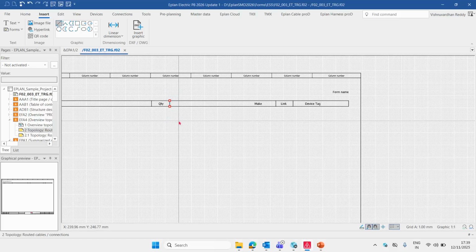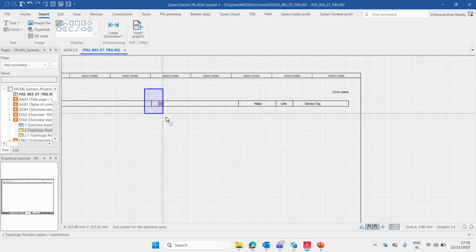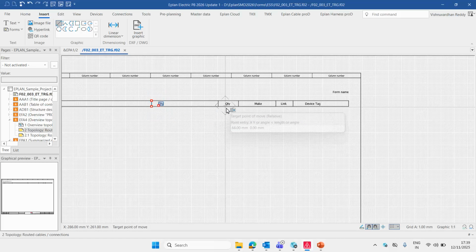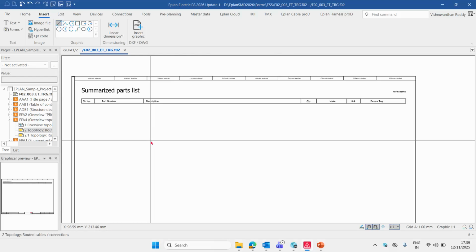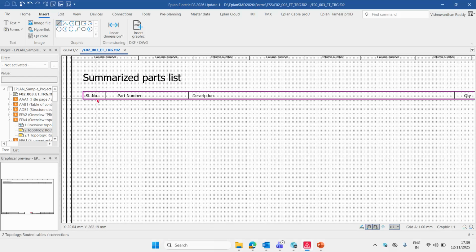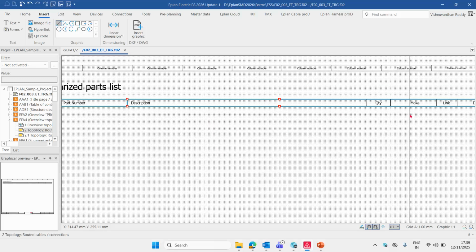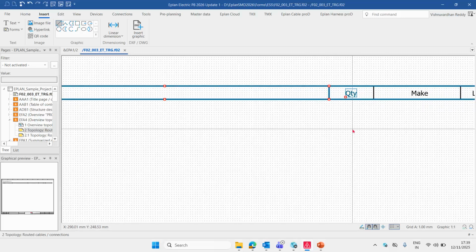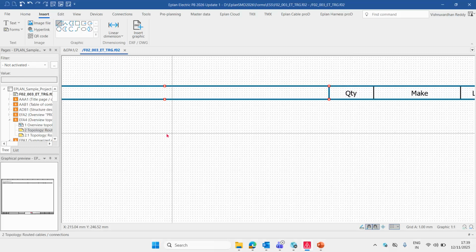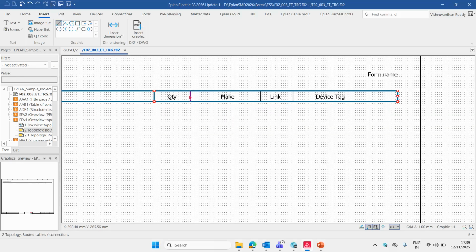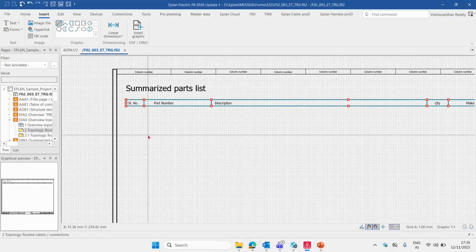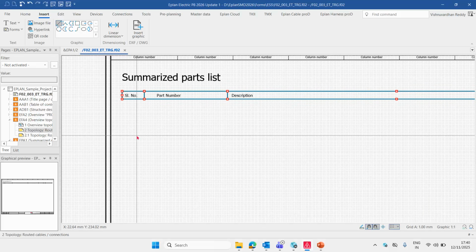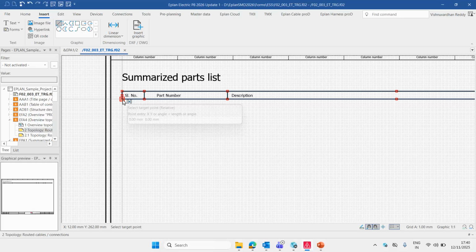So if you want the order number or any others, lot other things we can bring it here. So similarly I just want to push the quantity here. So I will be having a quantity in this fashion. So now I got a description. So now what you have to do it is I'll select these lines. By pressing Control, I'm making a selection. By mistake, if I select something, again press Control and select it, it becomes deselect. So this is the easiest way to do it. Then you will select all these boxes the way you wanted. Then the easiest way to make that replication below is press D, and it will ask that it is in the fourth quadrant, right?